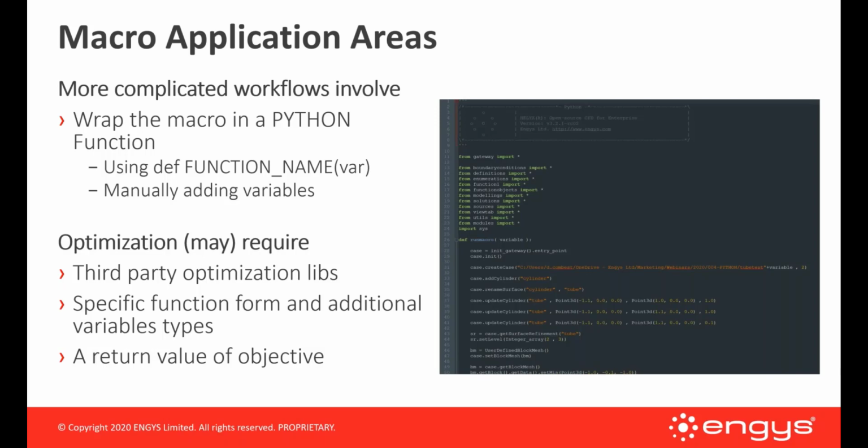So not just driving the analysis, the meshing, the setup, the solving, there's this contraction of data, summarization of data, and returning that as a value if you're doing an optimization. So averaging drag over the last 100 iterations, something like that.